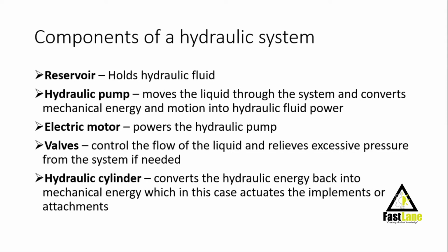We have components of the hydraulic system. One is the reservoir. The reservoir is basically to store the hydraulic fluid. It's where you top up the hydraulic fluid in case it is less, and it stores the excess in case the system needs more fluid. It's where the fluid is drawn from.